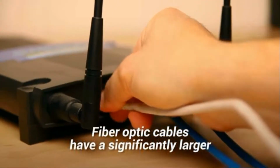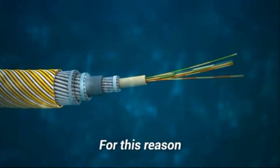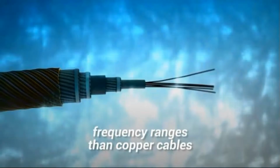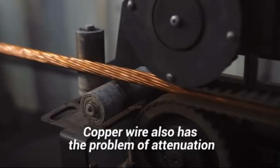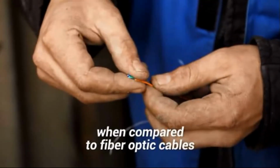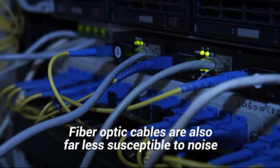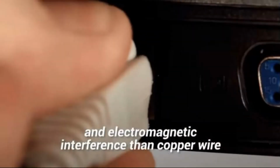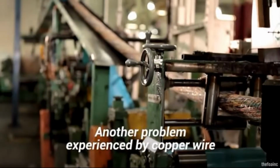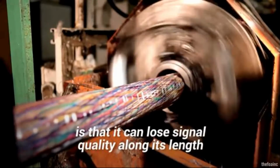Fiber optic cables have a significantly larger bandwidth capacity than their copper wire counterparts. For this reason, fiber optic cables can carry much higher frequency ranges than copper cables. Copper wire also has the problem of attenuation or signal loss at higher frequencies when compared to fiber optic cables. Fiber optic cables are also far less susceptible to noise and electromagnetic interference than copper wire, as the latter is made of metal. Another problem experienced by copper wire is that it can lose signal quality along its length.